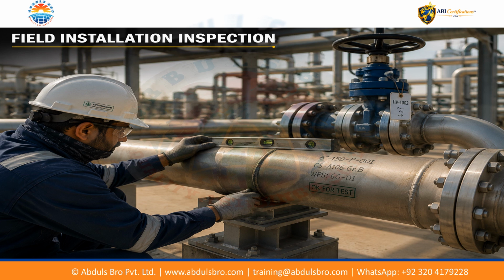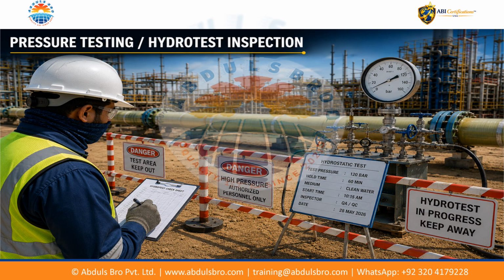Prior to testing, the system must achieve the required construction, inspection, and documentation status for release. Pressure testing is a critical verification stage before the piping system is accepted for service. QA/QC verifies the approved test procedure, test boundaries, test pressure, test medium, calibrated instruments, vents, drains, supports, and required temporary restraints. Required construction inspection and examination must be completed before testing.